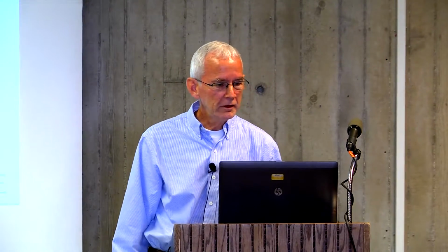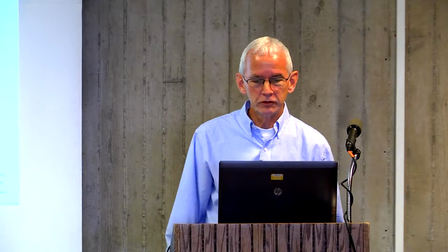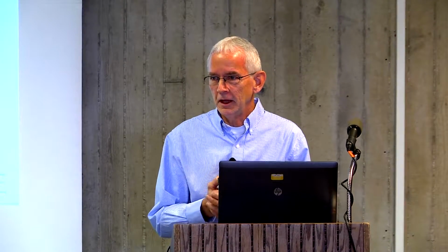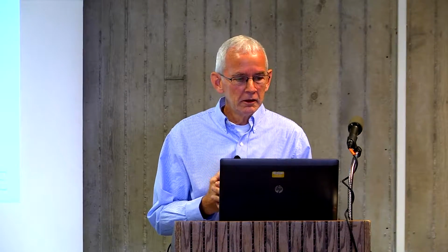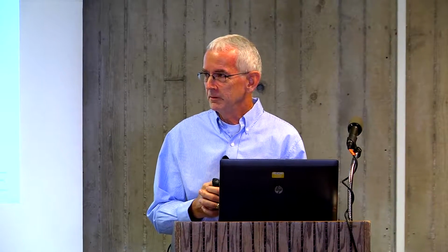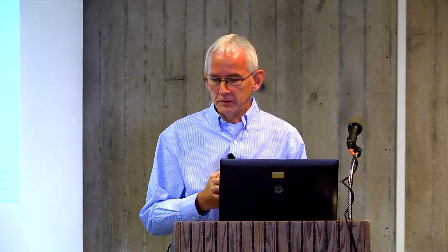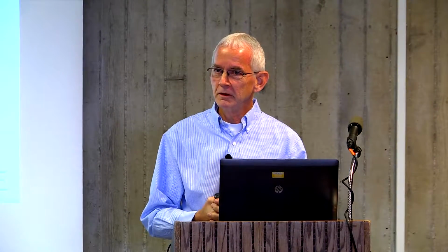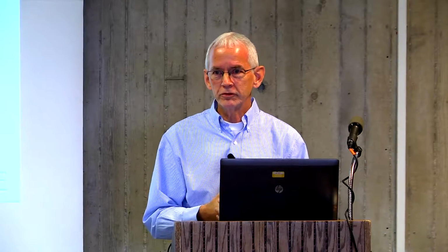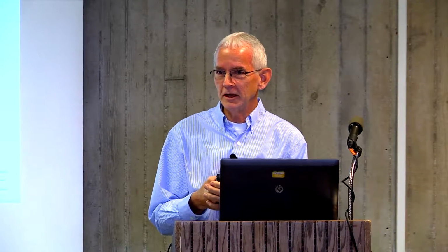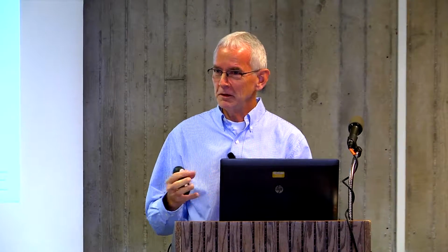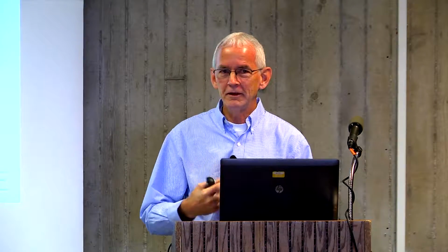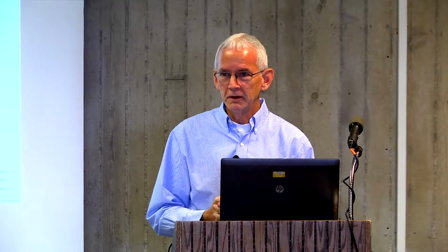Basically, the weight of the soil and the surcharge above it push the grains against each other and cause them to interlock due to friction between the grains. The soil at the surface doesn't have very much confinement, so there's not a whole lot of force pushing the grains together. So that soil can be more easily deformed. It has a lower bearing capacity than soil that is buried at a depth.